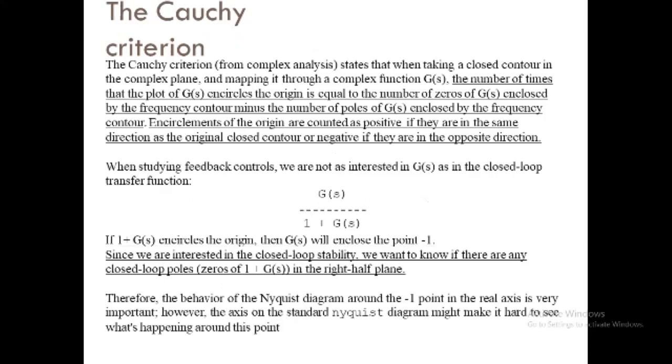Basically, the Nyquist plot also allows us to predict the stability and performance of a closed loop system by observing its open loop behavior. The Nyquist criterion can be used for design purposes regardless of open loop stability. That is, the Bode design method assumes that the system is stable in open loop, and therefore we use this criterion to determine the closed loop stability when the Bode plot displays confusing information.